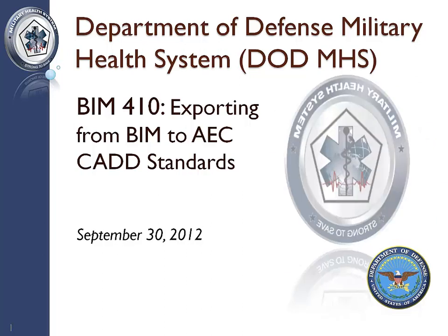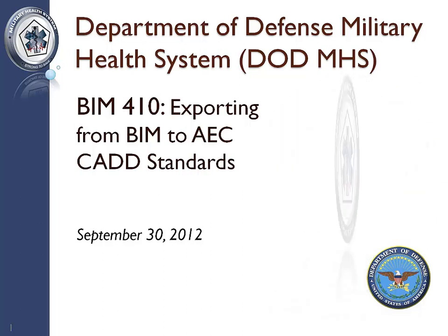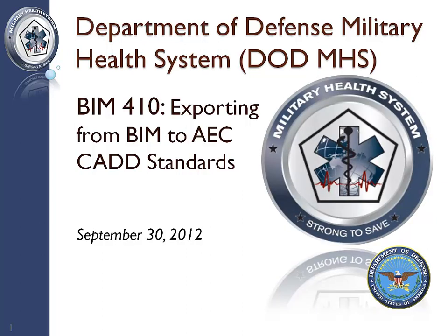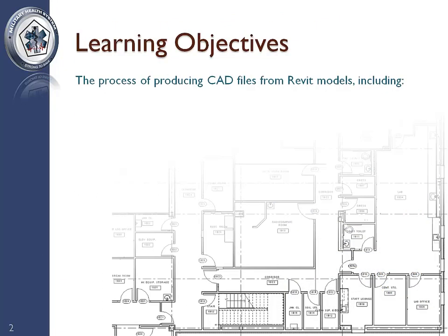Welcome to BIM 410, exporting from BIM to AEC CAD standards. This video provides an overview and demonstration of the export process from Autodesk's Revit BIM application to CAD DWG format files, compliant with U.S. Army Corps of Engineers, or USACE, AEC CAD standards for MHS projects. We will review how MHS project teams can produce AEC standard CAD files from their project BIM models in Autodesk